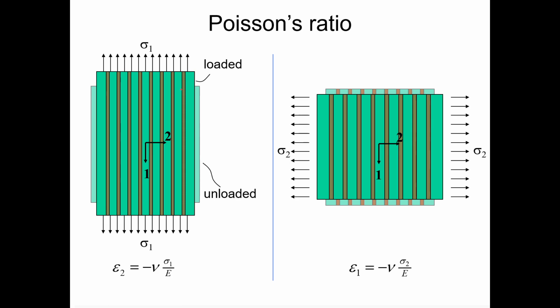As you can see here, if the fiber is aligned in one direction when you apply your loading, then you could actually cause some contraction. This is the original shape, and the elongated part is the deformed shape. As you can see, the material actually contract in the transverse direction. Based on the definition of Poisson ratio, basically you can work it out.